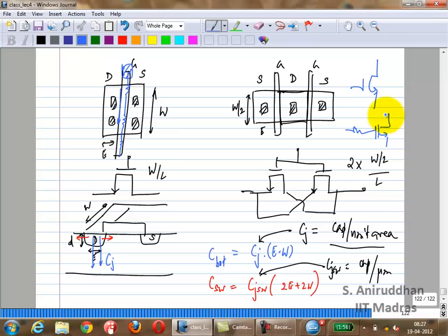Okay. Anything else? What else? What are the other effects of having a resistor? This is actually a physical resistor, right? Yes. Noise, right? So you can have gate resistance noise from the transistor. If you had a 200 micron long transistor, you will definitely see noise from the gate resistance. So splitting it into multiple fingers is very good. What else?